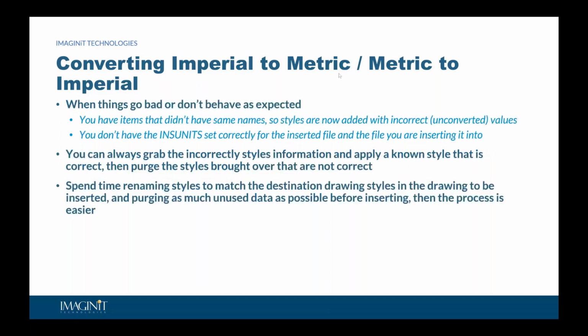And when things go bad or don't behave as expected, so you have items that didn't have the same name, so styles are now added with the incorrect unconverted values. If you don't have insertion units or INSUNITS set correctly for the inserted file and the file you are inserting into, those are the two things that usually cause the most problems.